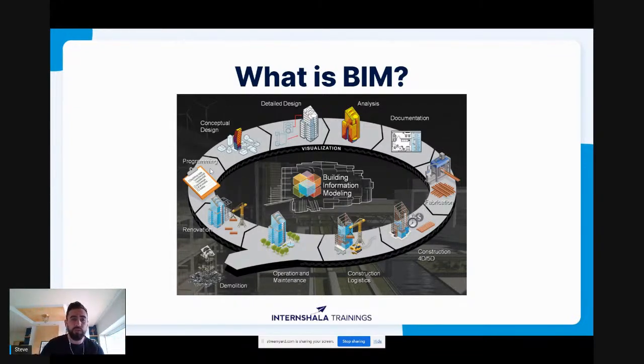Next, we move up to the conceptual design. So here, this is down to the architects and master plan architects. What they'll do is essentially like a blocking exercise. So there's no need to fully design the building at this stage. What we'll do is we'll take masses, like just rectangles, squares, this kind of thing, and we'll create a blocking exercise to create a visualization of what kind of concept we want to come across. So we don't want to spend all of our time fully detailing and choosing what walls or windows at this stage. That's the next stage. So this is the concept design stage.